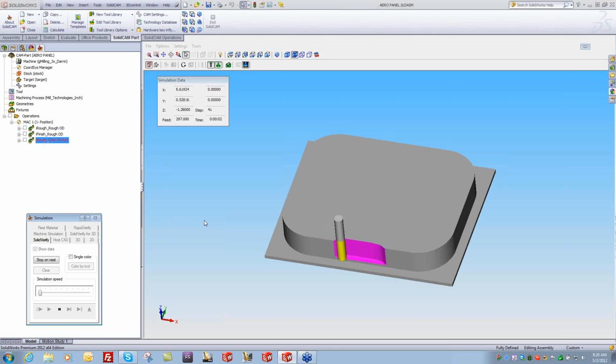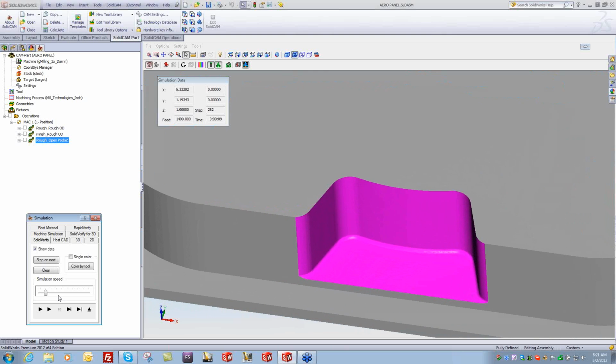You can literally program your entire part with iMachining. You can even do holes. You can interpolate holes if you had to. Generally, you're going to drill holes, but I have done some testing in the past where we compared helicaling out holes versus drilling them, and we could actually beat it. So let's zoom up and do that again.